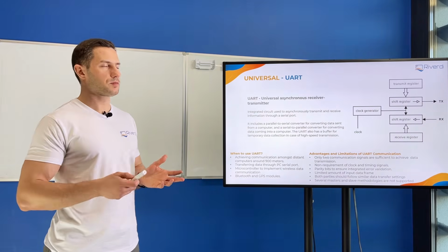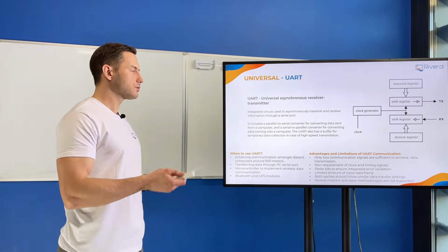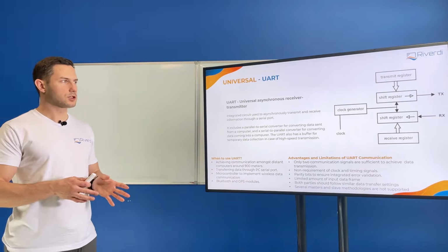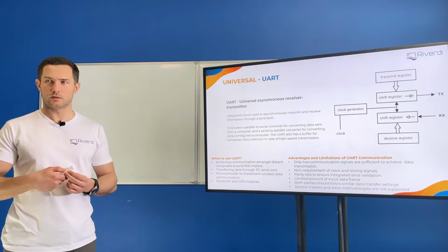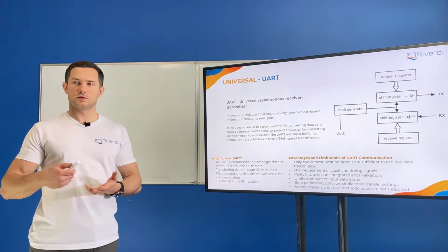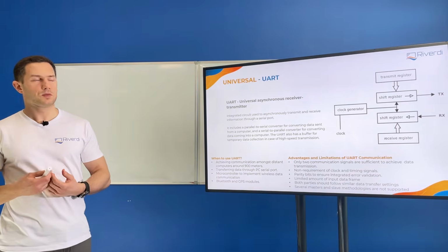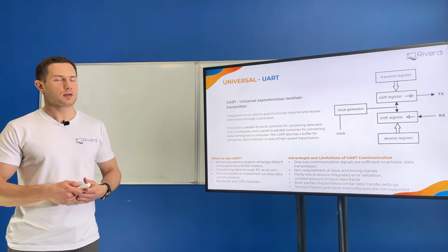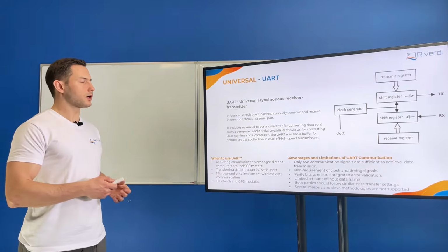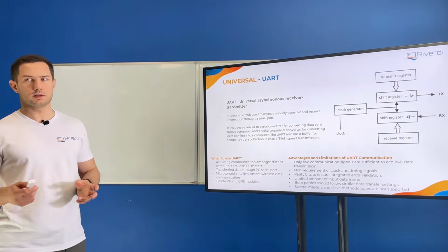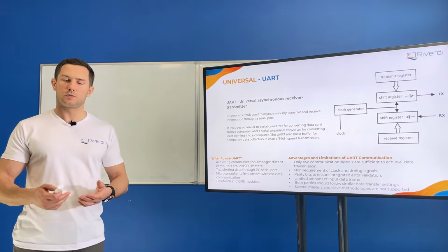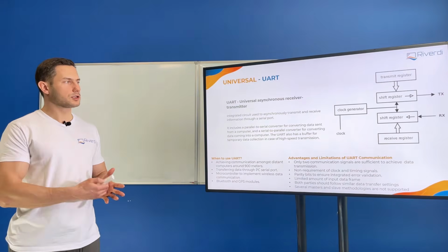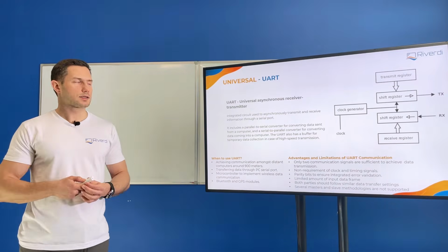So maybe UART or SPI or I2C, they can be used for displays, but as I mentioned, for low resolution displays, could be SPI, but for high resolution displays we need intelligent display. So we need a display that will generate the image internally, and through these slow universal interfaces we only send commands, or maybe we send image once and it's being stored into the internal memory of intelligent display that we will use later, sending the right command.